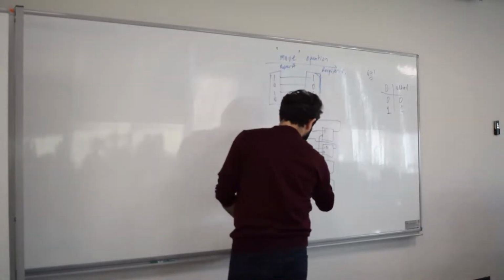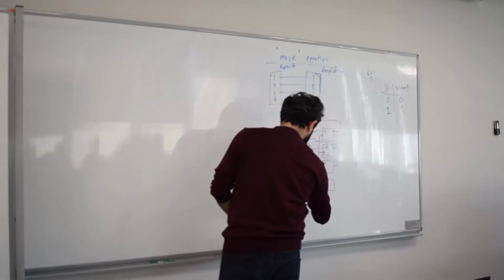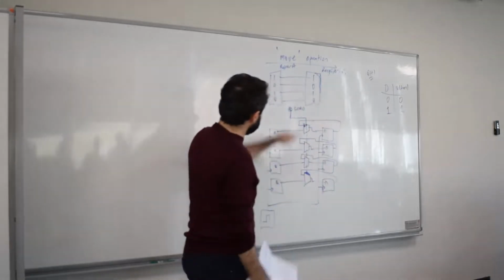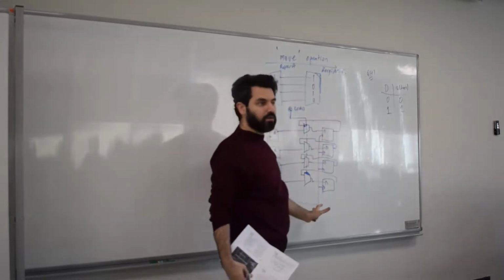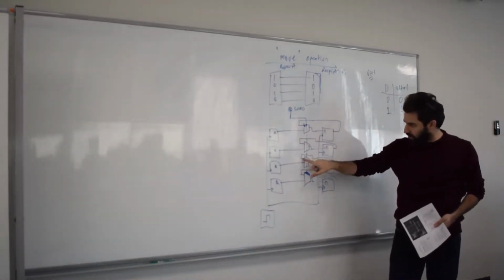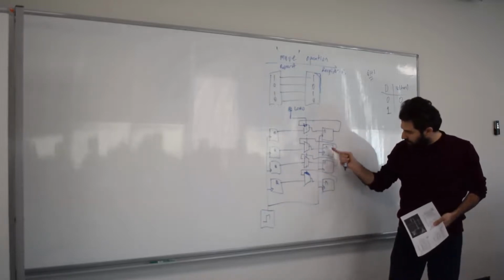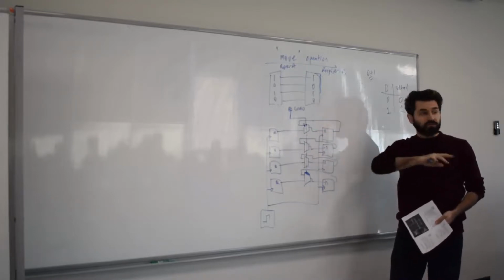I've got another mux here, and then I have another feedback. And then finally, I need another mux here. So I got that. This is my D, and this is my control signal. You see the control signal load actually controls this mux, this mux, this mux, this mux. They're all in parallel. So whenever your load is 0, that means you select this one, this one, this one, this one, which means all of the bits stored in the D flip-flops will be your next state, and next state, and next state, for as long as you want.